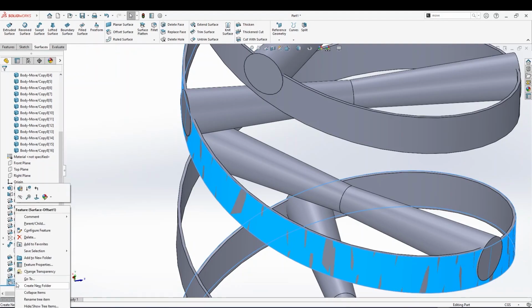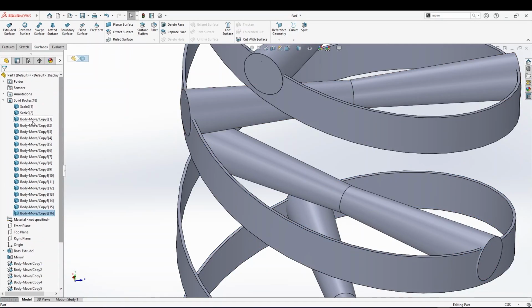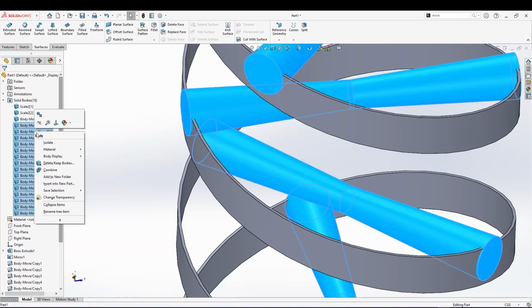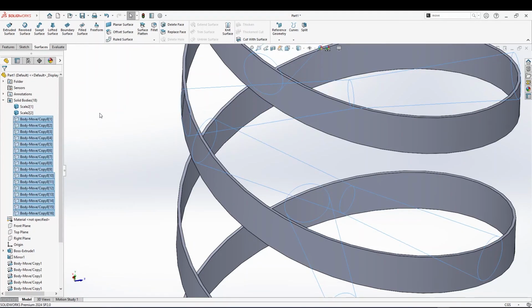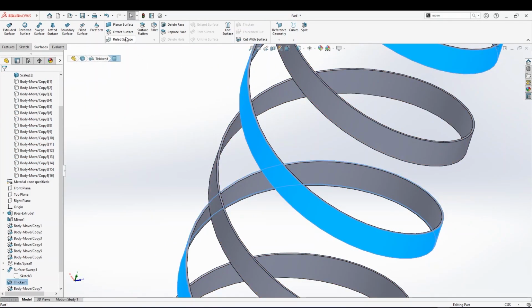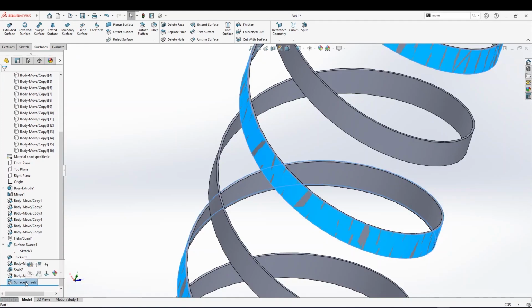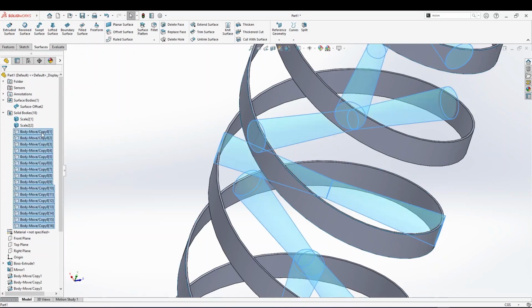What I need to do first, let's delete it and make it a clear, smooth surface that completely follows the spiral. I don't want these bars to be in any connection with the surface that I get, because I want something clean. What I do now, I will hide all of them for some time. Just press Shift. All of them I'm hiding. Okay, now I don't see them. And now I can convert this face into a surface, because in this case everything will go smooth. Offset Surface, 0 distance. Okay, it's good. Now it's a separate surface. And now I make all of them visible again.